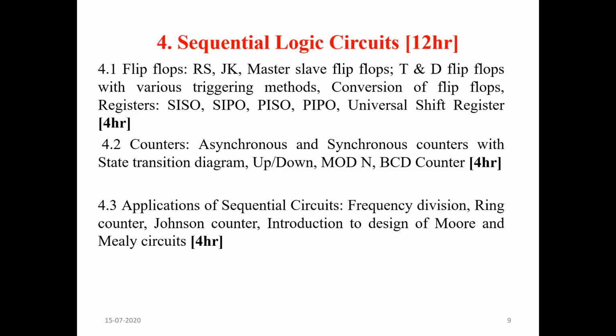Like for example, your SISO. SISO's full form is serial input, serial output. When you give your input to a particular circuit in serial form, that is SISO. For example, you give 1, 2, 3, 4 into your circuit, and at the output, how do you get it? You get the first one, then the second one, then the third one.